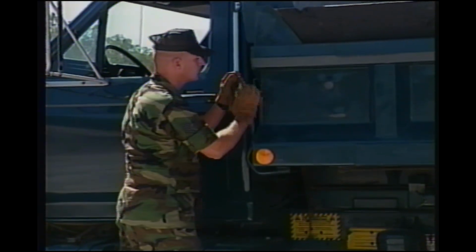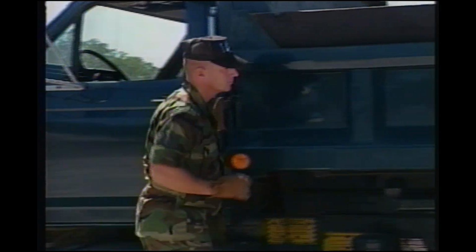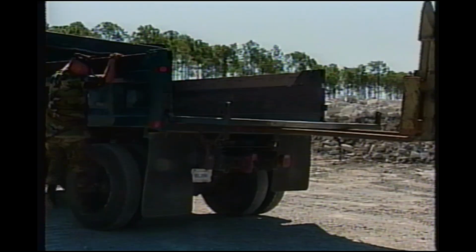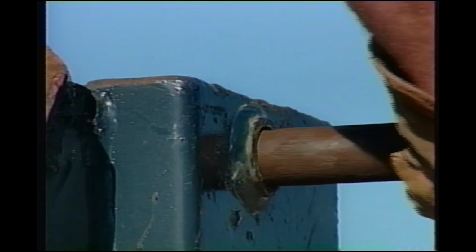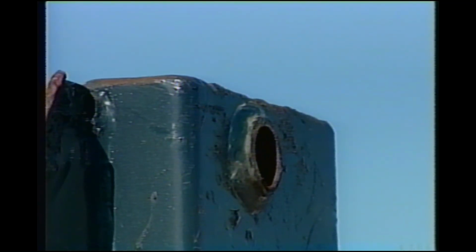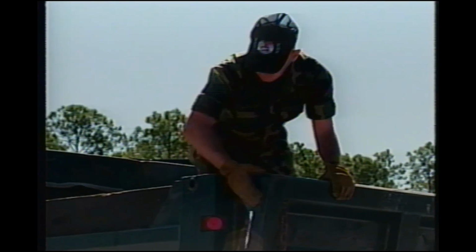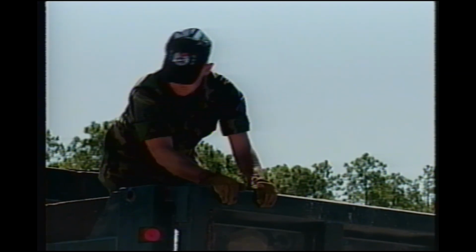With the tailgate in place, raise the tailgate locking lever to the locked position. Double-check the connection to make sure the tailgate is securely attached to the bed. Remove the hinge pins at the top corners of the bed. Rotate the tailgate up and over until it fits snugly against the bed rails. You might have to slide it one way or the other to fit properly.